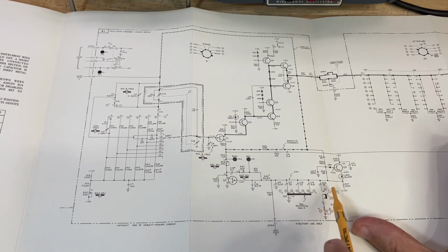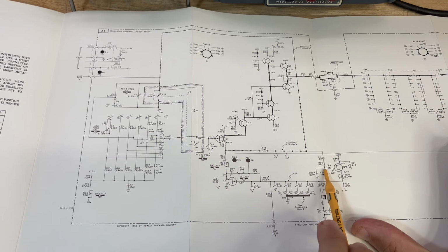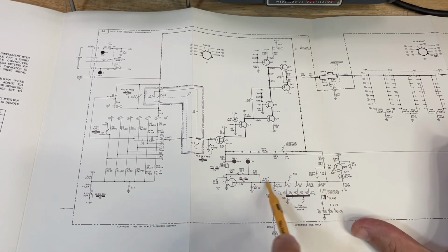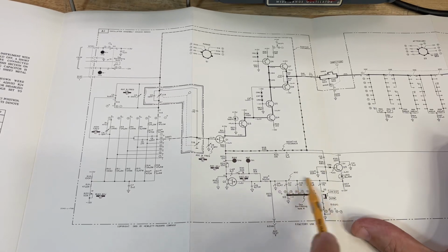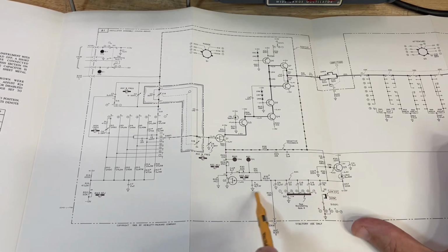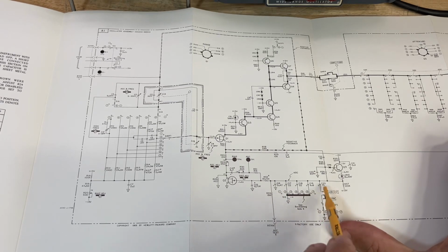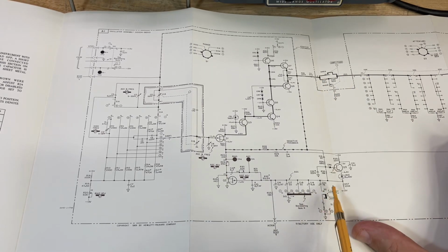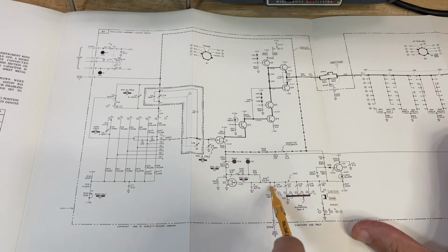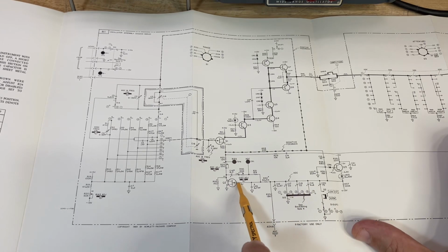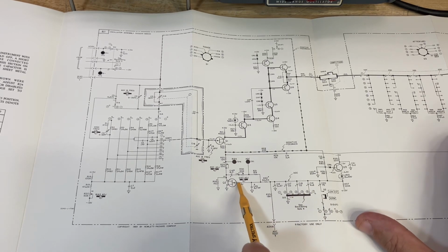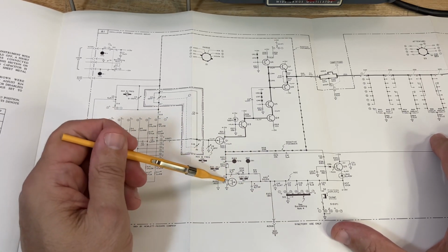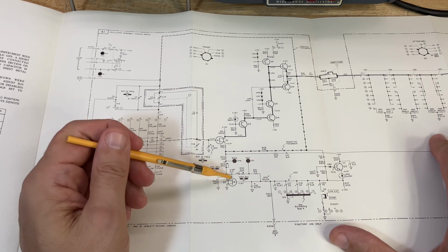level shifting, and basically a diode detector here provides a time constant and a resistance, a time constant that's selectable depending on range, so that you can track the envelope of the amplitude without tracking individual cycles. That voltage is applied to the gate of this feedback FET Q2, which takes the place of the light bulb in the 200 CD basic oscillator circuit.